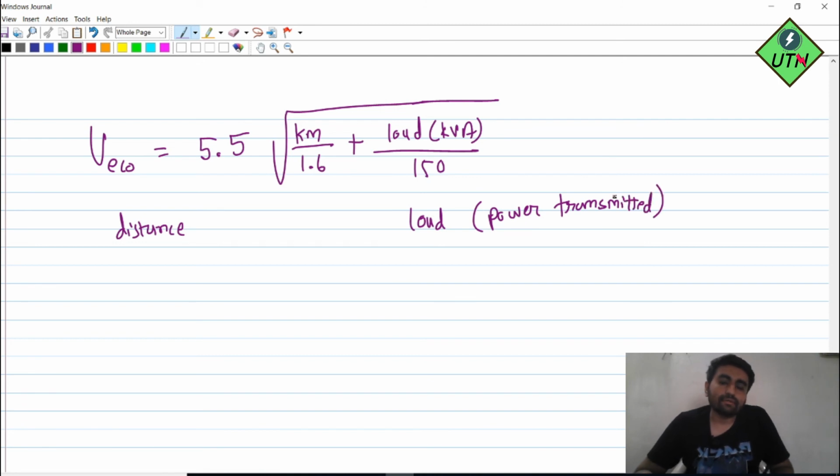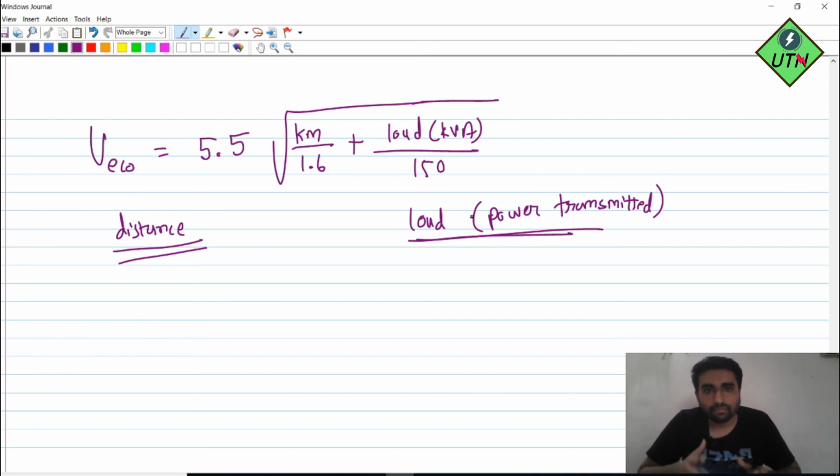See, when we are designing a particular voltage for transmission, these two things we cannot ignore. These two things have a considerable amount of influence on the economics of the transmission voltage, or the cost of transmitting a particular power. So we cannot ignore these two parameters. Here we can see that if we increase the distance, the cost of terminal apparatus is reduced.